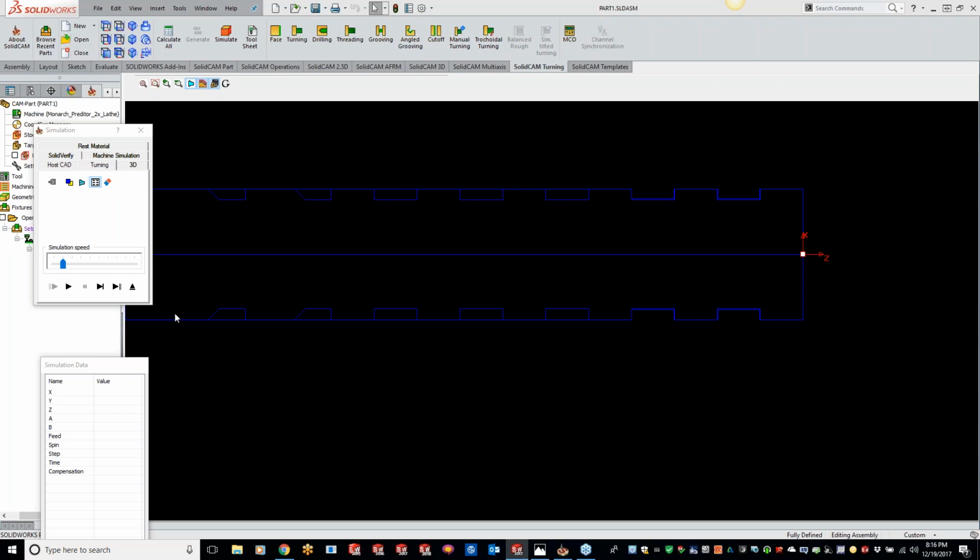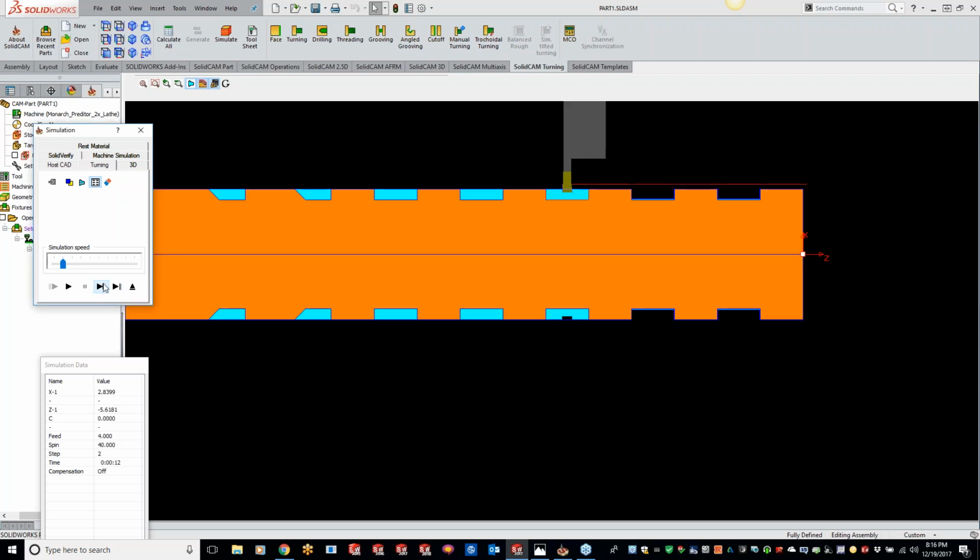Yep. That's kind of getting the chips out of there. You're not putting a lot of stress in certain areas. So by doing the alternating, you're kind of working over here, then you're bouncing around, so you're not producing a lot of heat in just one spot, and kind of dissipating the heat a little bit. Yep. Kind of what I was thinking. Ronnie, you are good. Didn't even think about that. So. Nice.